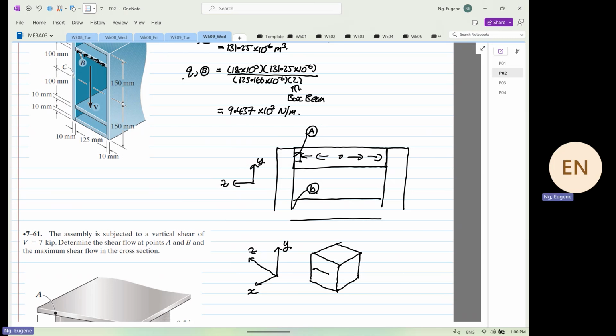We know that this is our shear flow direction, but what is it? The intersecting plane, this intersecting plane is which plane? Anyone? This plane will intersect which axis? It's parallel to Y, it's not intersecting Y. So if I draw this plane over here, can you all see what plane it is intersecting, yes or no? So it's intersecting the X plane, and the shear flow is in which direction? Z direction. Are we clear? So that is the direction of the shear stress that we are looking at.